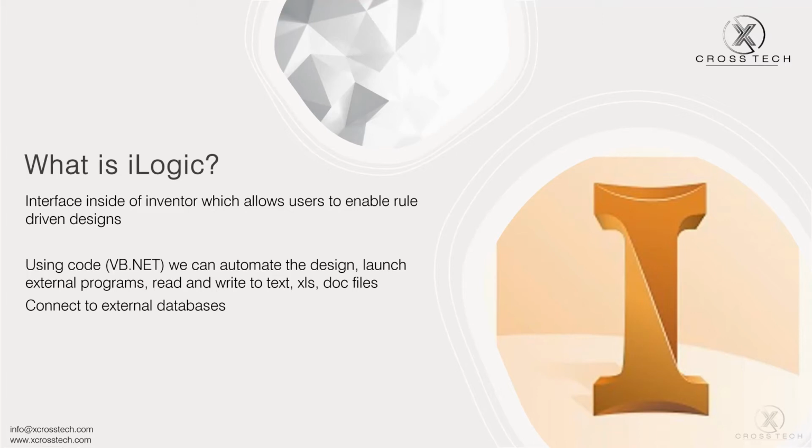It's a tool or functionality of Inventor that allows you to create logic in the form of VB.NET to accomplish these tasks. So the rules are developed and organized using snippets or other code writing statements to run at given times. These are known as triggers inside of Inventor to consistently do some of the work that your engineers or designers need to do.